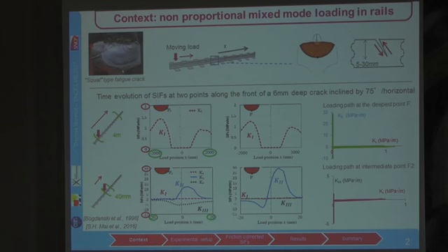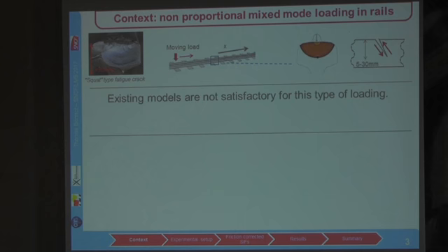But in fact, the crack keeps propagating in the same plane, and so existing models are not satisfactory for this type of loading, and we can wonder how to predict the crack path and crack growth rate in this case. So this thesis is focused only on crack propagation and for quite long cracks.